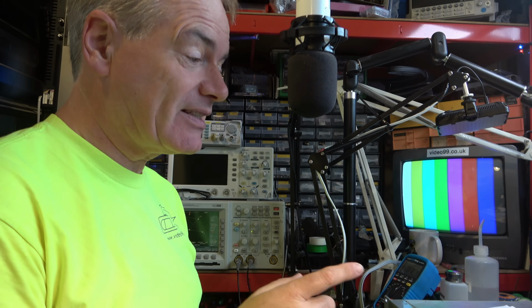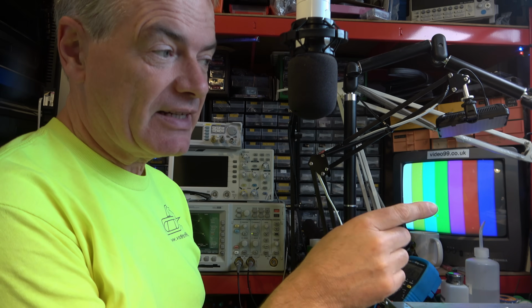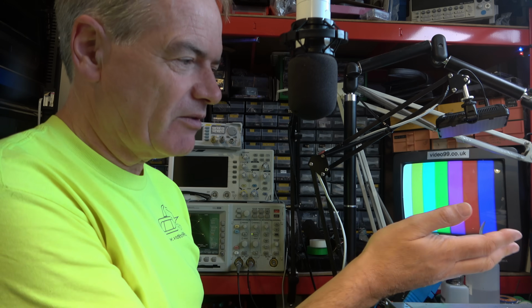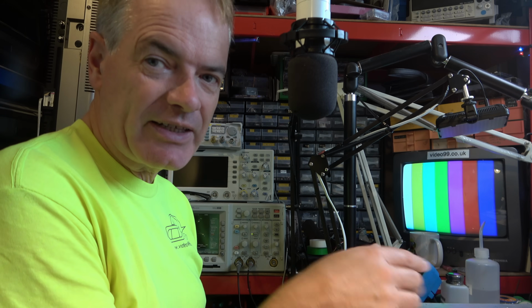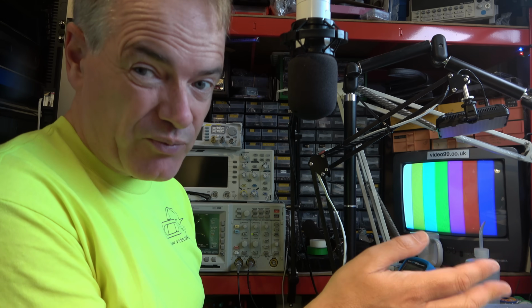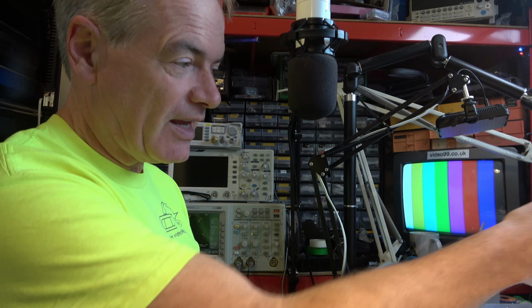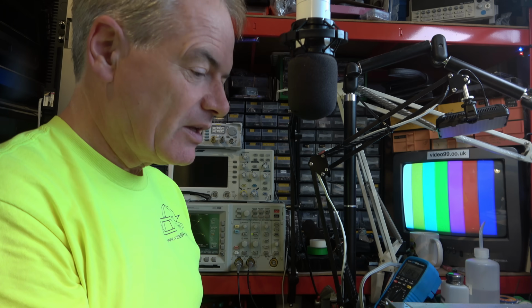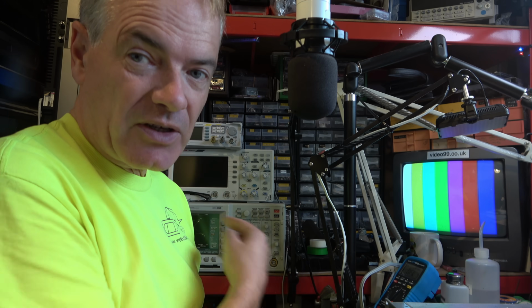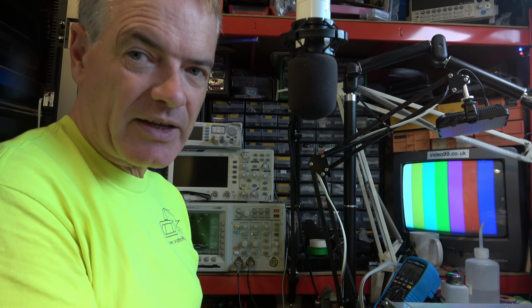And it should be said that what I had done this time is connected up loads. So I know it's supposed to be 75 ohm. The resistors I had to hand were 180, so I used pairs of those. So we've got about 90 ohm load, which is probably close enough that the outputs are feeding a proper load. So I don't know why we're getting such a grubby response on the oscilloscope as a vectorscope.